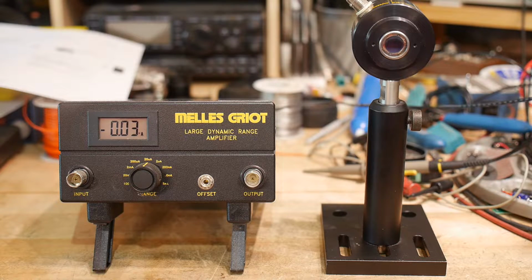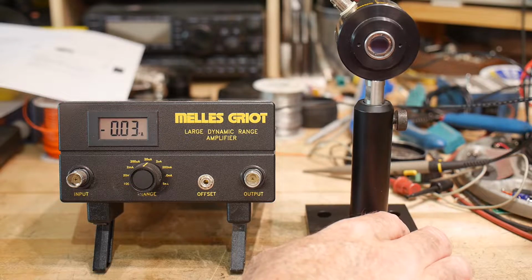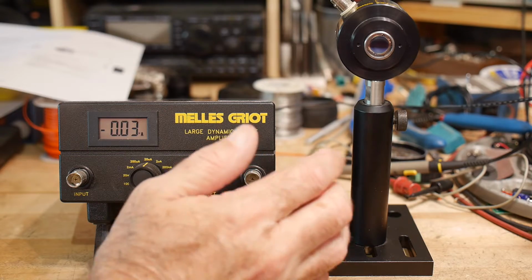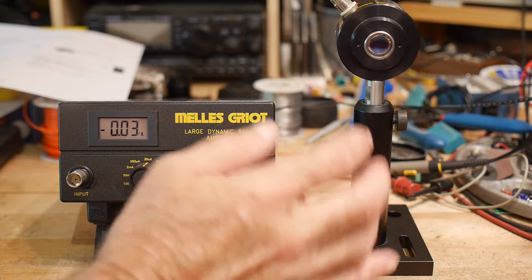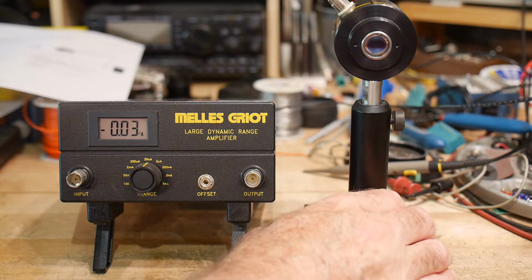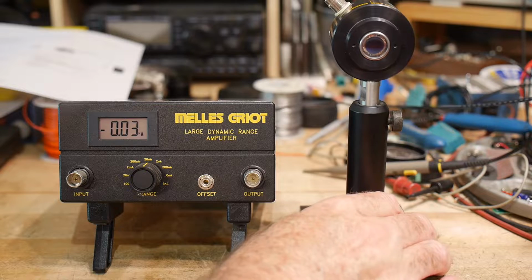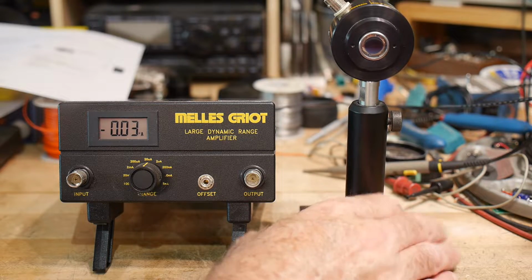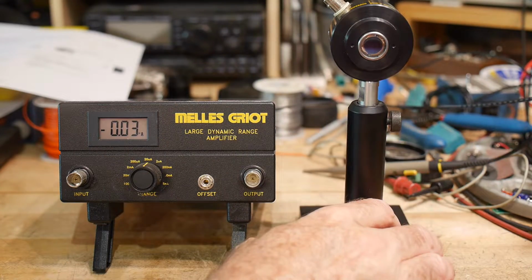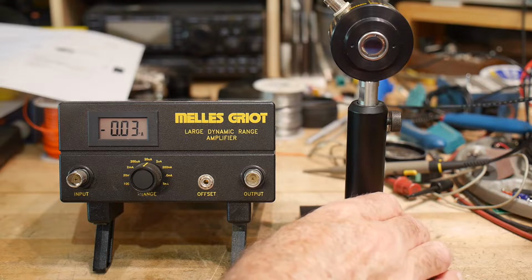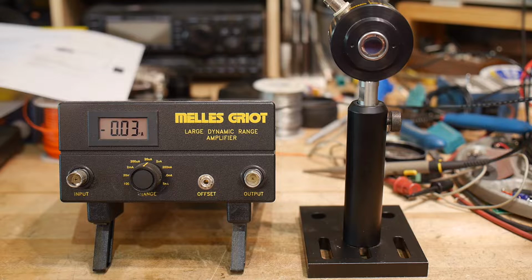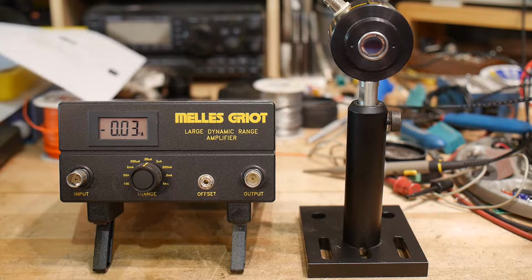So if you're an optics engineer, you probably would have something like this. This is a photodiode, and this is an amplifier. In order to use a photodiode, you need to amplify its signal and figure out how much photocurrent the diode makes. We'll talk about photodiodes, but basically it generates a current depending on how much light falls on it. It converts photons into electrons and gives a current.